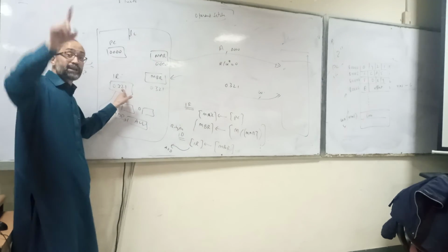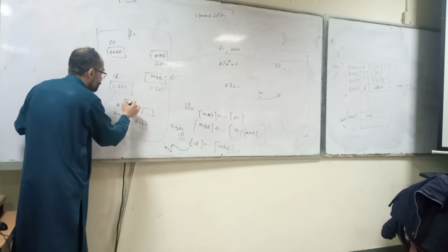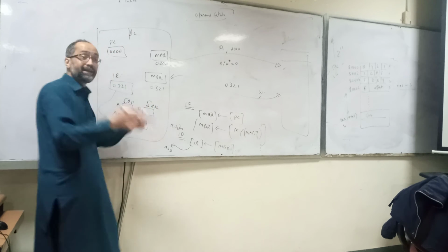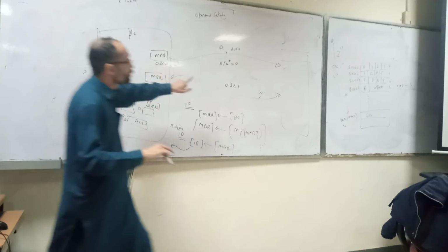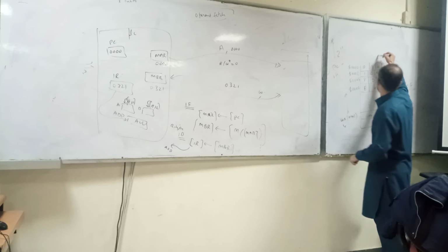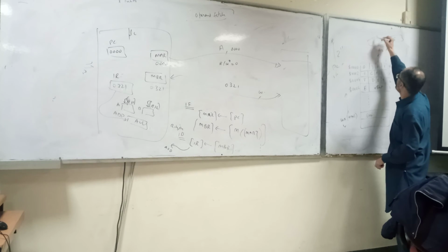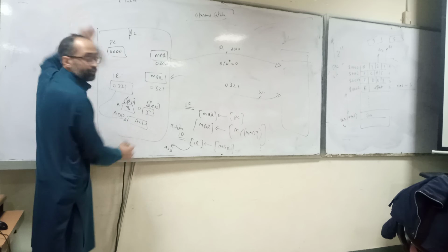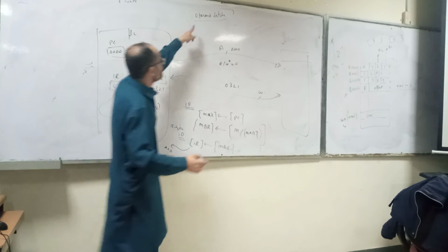So it will check the RS1 field and the RS2 field. The RS1 field will go to A, the RS2 field will go to B, and the contents of RS1 and RS2. Now let's assume we are adding R2 and R1. Let's assume the contents of R1 is 5 and the contents of R2 is 3. So those values from R1 and R2, 3 and 5, will be loaded into this.